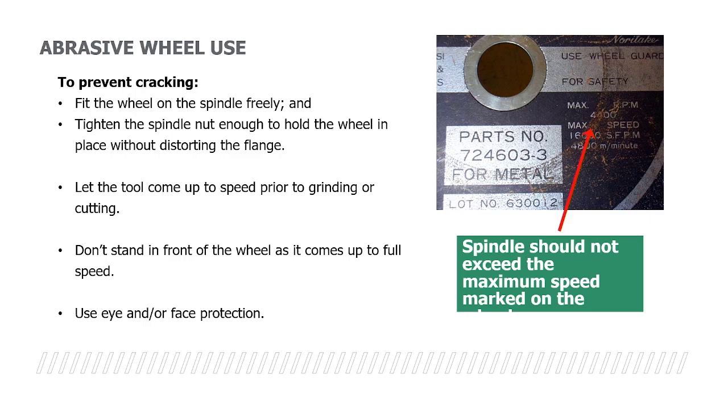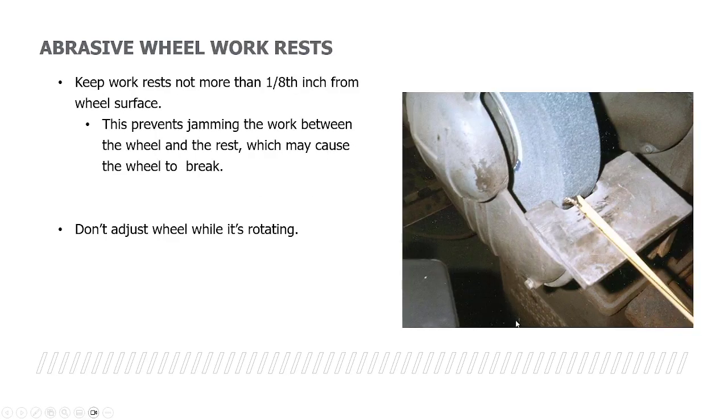Let the tool come up to speed prior to grinding or cutting. Do not stand directly in front of the wheel when it comes up to full speed, and make sure you're wearing safety eyewear, goggles, or a face shield. Those are all designed to protect the eye from what? Flying debris.